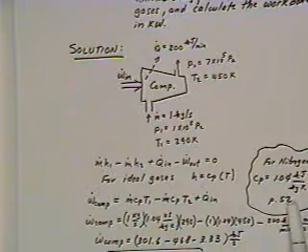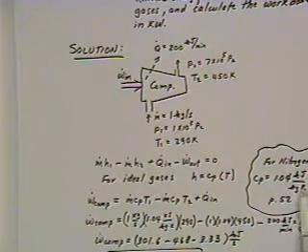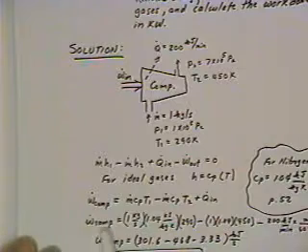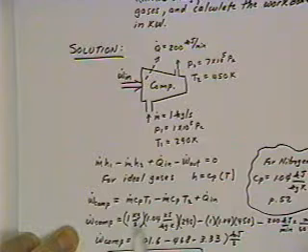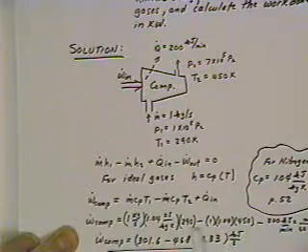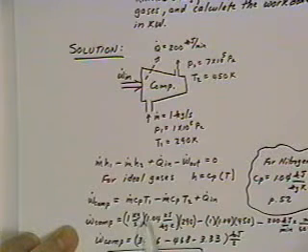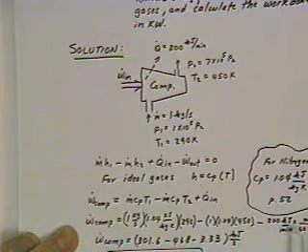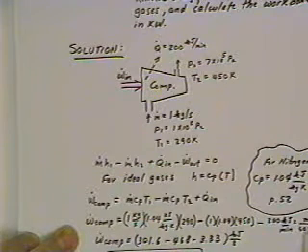Nitrogen, again, goes to page 52. Look up the properties here for the nitrogen, and we'll see that the CP is 1.04 kilojoules per kilogram Kelvin. And so now the work of the compressor, which is what we're solving for, is going to be equal to the flow rate, m dot, of 1 kilogram per second times specific heat times the delta T term. This gives you the term for the change in enthalpies. You've got kilojoules per minute for the heat loss, so you've got to convert that into seconds because we want this in kilojoules or joules per second, and so that's dividing by 60.